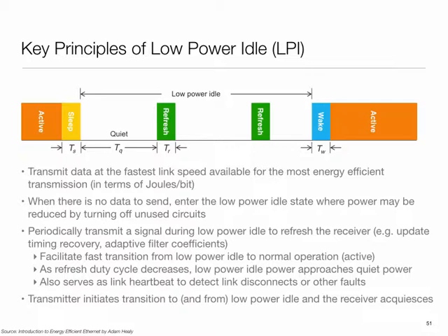In a nutshell, scaling didn't work out because in a processor, scaling is easy. You change the clock, it runs at a different speed. In a communication setting, scaling is hard because every time you scale, you have to relearn the channel characteristics, and therefore the delays involved are too complicated. So what won out on the communication side for Ethernet is just simple shutdown, coupled with some periodic refreshment messages. At some stage you decide to go to sleep, and you sleep, but you keep a heartbeat going so that you can rapidly wake up.